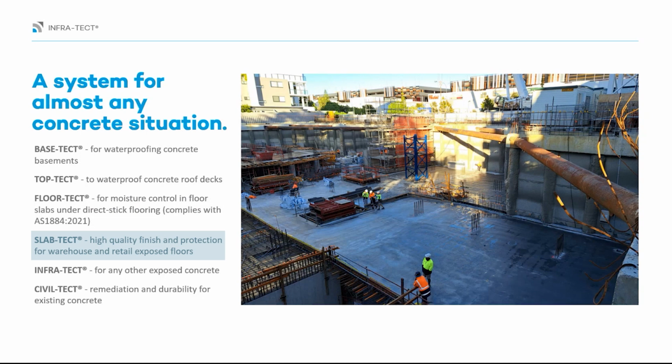SlabTech's a really cool one. Again, high quality finishes for things like warehouses, showrooms, museums, and art galleries we've done recently. So, things where you want a really high quality concrete floor. Quite often they're treated with polish and coatings on top that have hugely high maintenance and lose that shine over time. We have a system that we can incorporate to get a really nice sheen from day one. And the interesting thing is as you wear it out, you actually enhance that sheen. Exactly right. It's not the other way around like you'd get with a topical sealer.